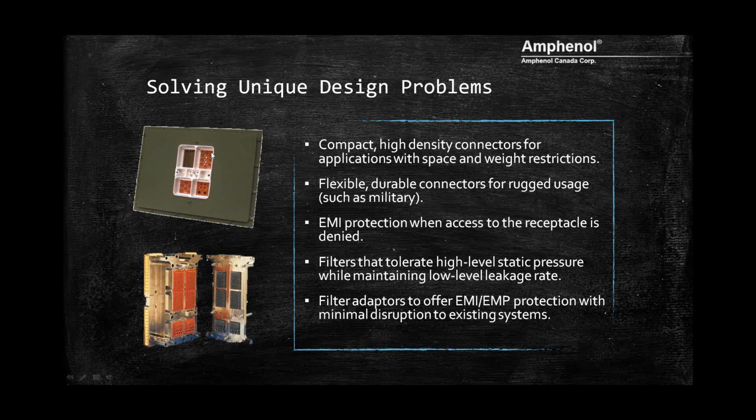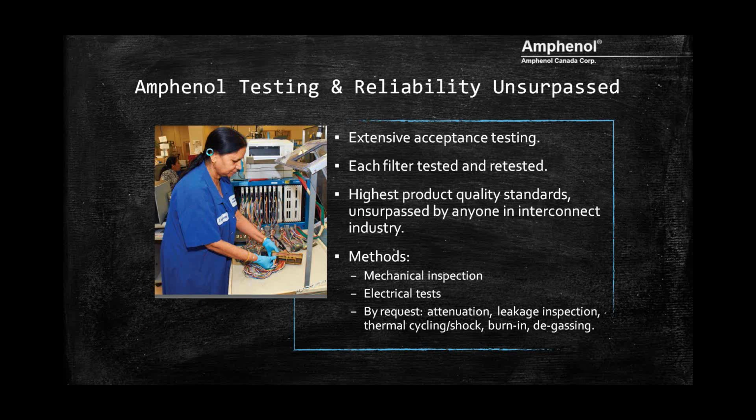We have the ability to do measurements using insertion loss cells, which house the connector. And we also look at mechanical inspections, electrical tests. We look at leakage, and we also have the ability to do thermal shock and cycling and burn-in. For those of you who have space applications, we degas our connectors as well so that components will not leak out any gas into your system in space applications.